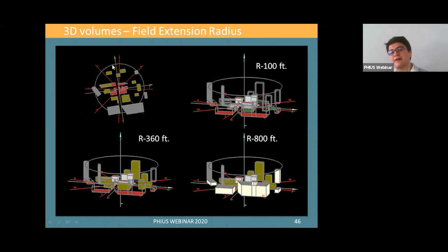So the idea is that these circles don't really touch. If you have a two-story building, you try to make a distance from the circle. The circles are not accounted for in the shading calculation. These circles are modeled just to make sure that once you import your geometry into WUFI, the project geometry locates at the ground level. So it's not that important.